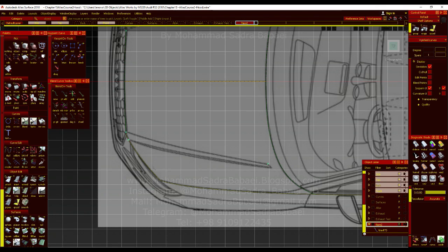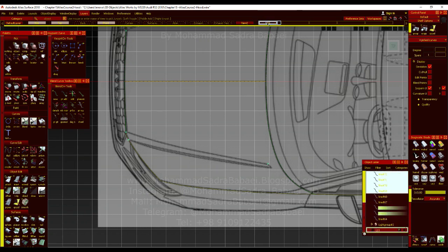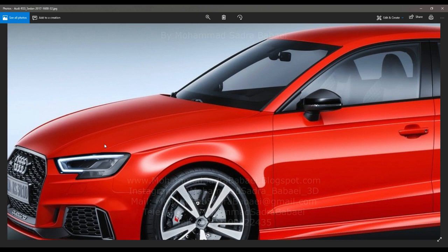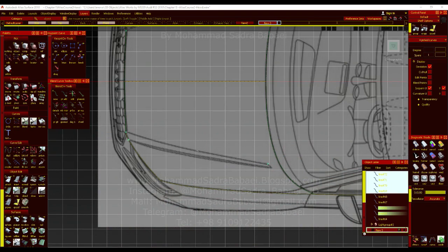Okay, now let's start. One of the important things is that sometimes I can't create these surfaces. Let me just add these curves to a new layer. We can create one main surface from side to the middle of the hood, and then project these lines into that, and then trim it, and after that we can play with the surfaces with the draft tool or freeform blend or anything you think is the answer to create the shape.